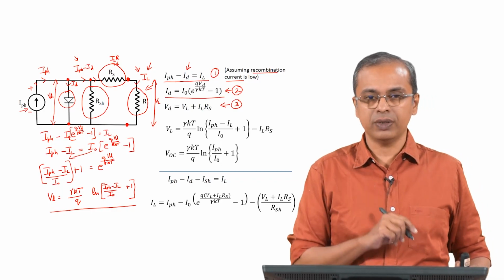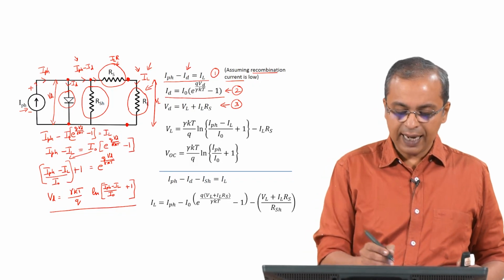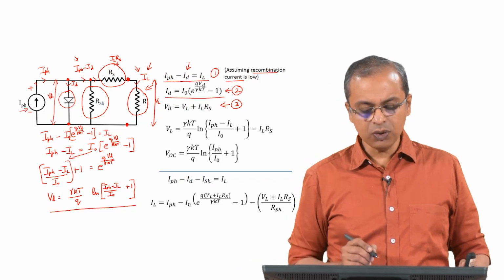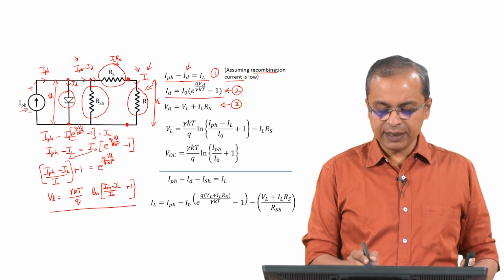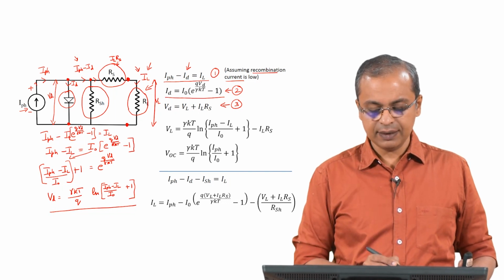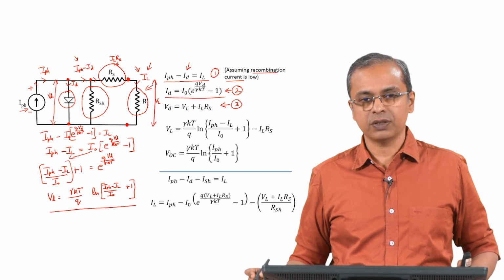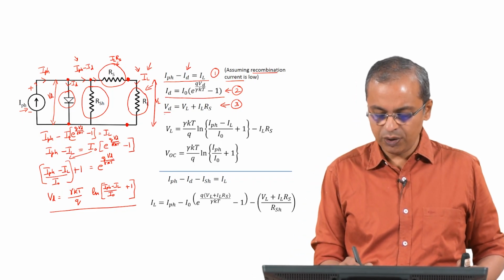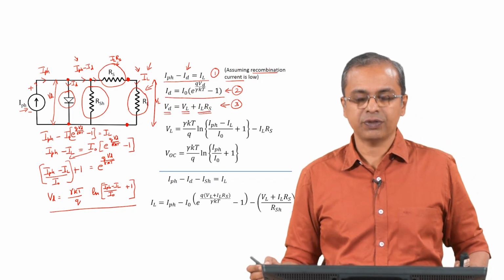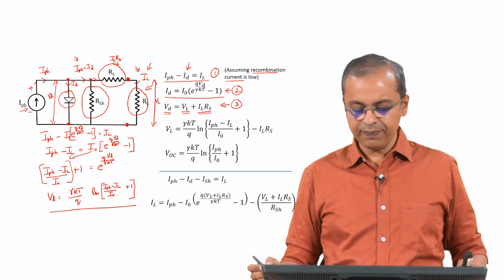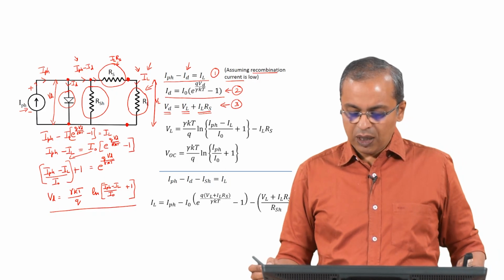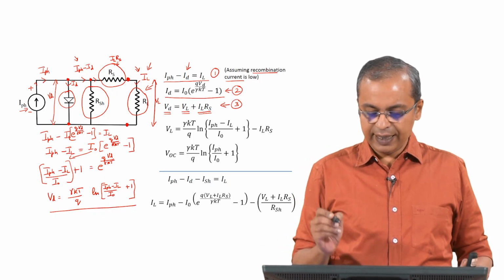It is also the current that is going into the series resistor, I subscript L, and the resistance there is this series resistor RS. So, therefore, the voltage on the load plus the ILRS together will equal the voltage across the diode. So, that is what we have here: the voltage across the diode is equal to the voltage across the load plus the IR drop on that series resistor. Okay. So, Vd equals VL plus ILRS. Now what we are simply going to do is rearrange this.